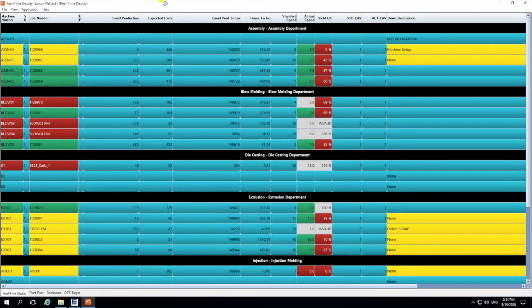The other information we have is goods production. This is currently based on the current counter of the machine as well as the signals that are connected to it, either based on cycle times, or if we're running on an encoder, which measures pulses per minute, which can be converted to meters per minute, or if we're measuring in an assembly department, the amount of parts assembled per minute. It's all dependent on the shop application, whereby there are numerous production standards we can measure against.